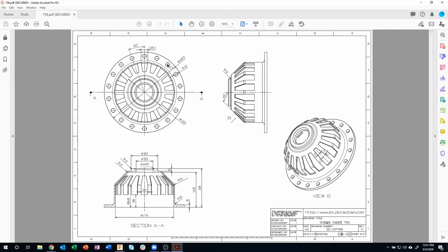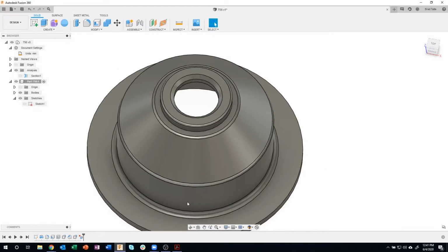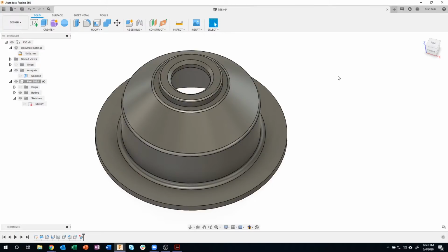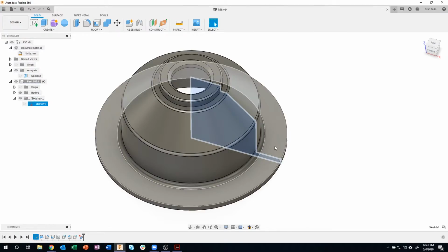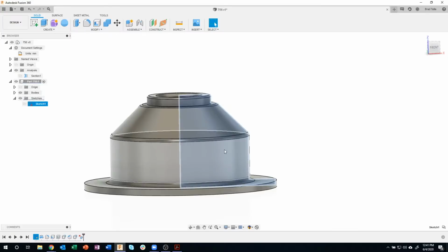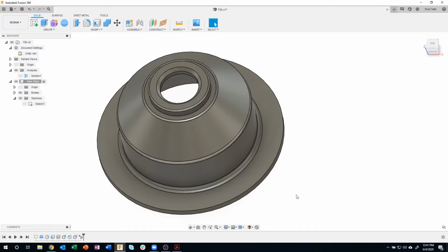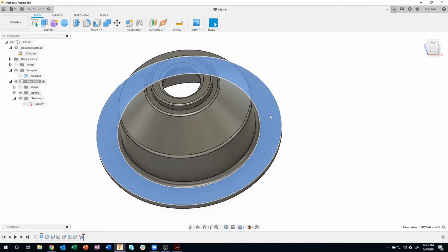I'm going to figure out how to put these holes directly centered on this little flange right here. So typically you would see a circle that goes through all these and a radius that defines what that would be. So diameter 12, and we'll put it on this face right there. Okay, I see this question a lot. Should I go back to my original sketch? Well, I can't, right? I did my sketch on my front plane and I need to do it on my top plane. So some people like to have the minimal number of sketches as possible. Okay, so I'm obviously going to have to create a sketch.